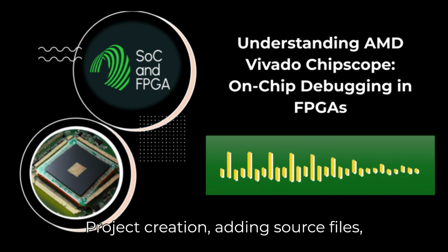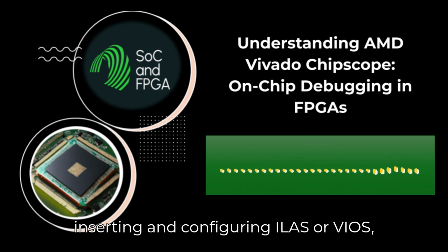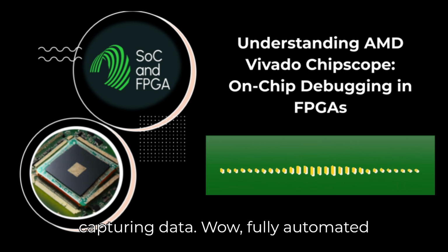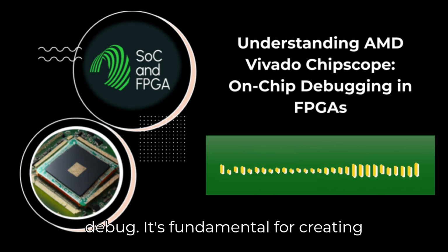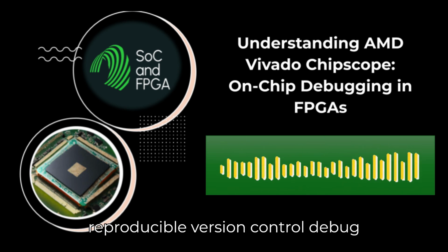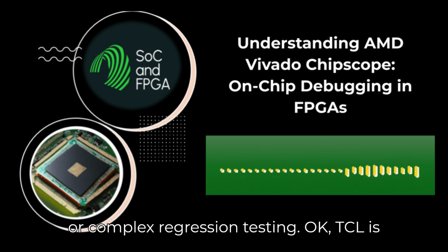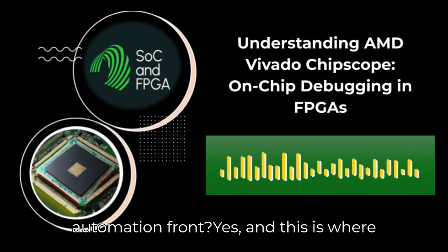Project creation, adding source files, inserting and configuring ILAs or VIOs, running implementation, programming the device, even setting triggers and capturing data. Wow, fully automated debug. It's fundamental for creating reproducible, version-controlled debug setups, essential for team environments or complex regression testing. Okay, TCL is powerful. Anything newer on the automation front?